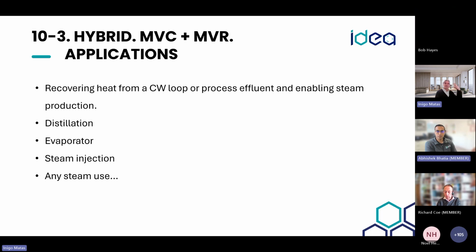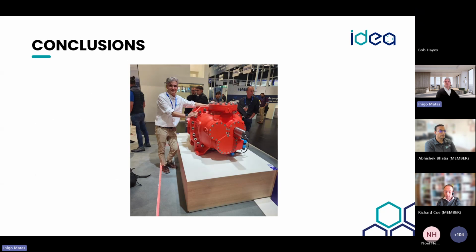We cannot really go higher when recovering the energy because that will affect the quality of the product. A good one that I really like as well is that sometimes implementing a heat pump can be complicated because there is not a lot of space. Here we just need to make a tie-in on the cooling loop and take it somewhere else where we can implement the heat pump. Okay, so we have gone through all the different parts.